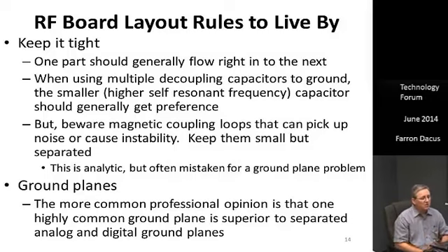Another place I've seen these magnetic coupling loops cause a real problem is coupling in the noise of, say, switching power supplies. Everybody's gone to switching power supplies these days, but in RF it's a very bad idea to run sensitive RF circuits straight off a switcher, so there's usually at least one intermediate stage of linear regulation, and often 2. So you may be surprised sometimes when you set up a switching power supply, and then you have 2 regulators following it.